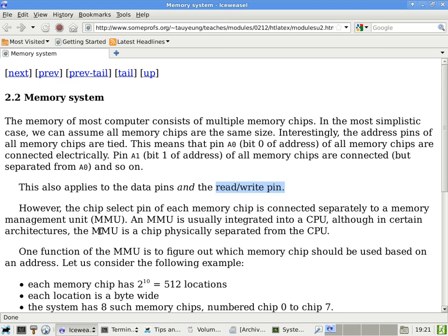Okay, this is 64, this is 128, this is 256. I should not have 1 for 512, because the entire chip only has 512. So maybe it's a 9-bit address, not a 10-bit. I messed up originally because it only has 9 address lines. So this is my A0, and this is my A8, not A9, sorry. My bad.